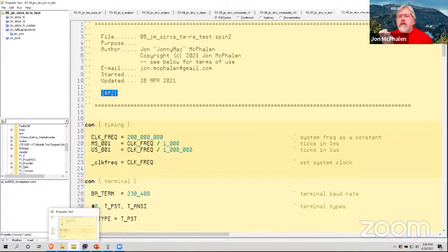And I would say any of you that are doing commercial applications, do look at the data sheet because they'll show a little RC circuit attached to the power supply. You want to put that on there. That will make the operation of these much more reliable in commercial apps.